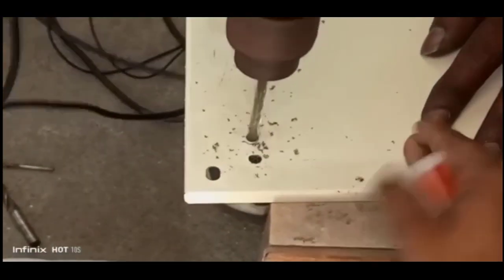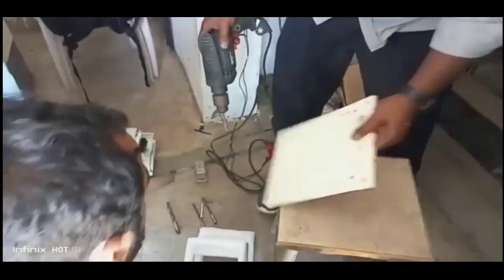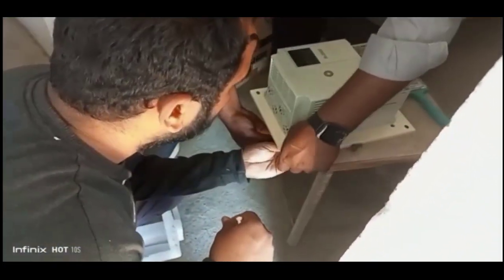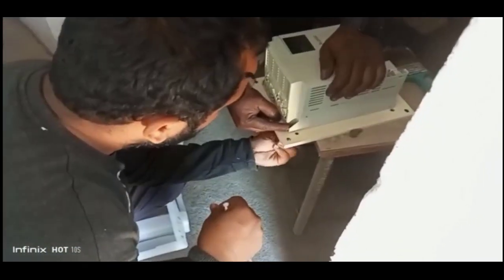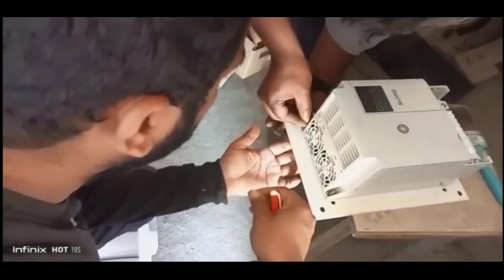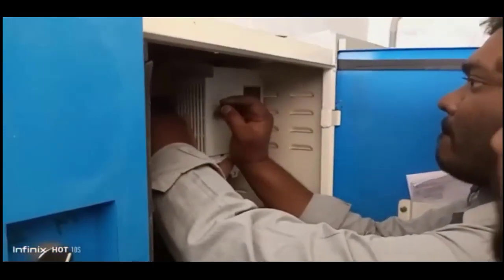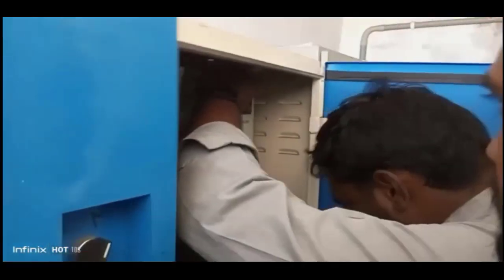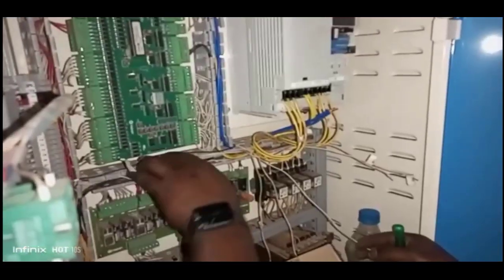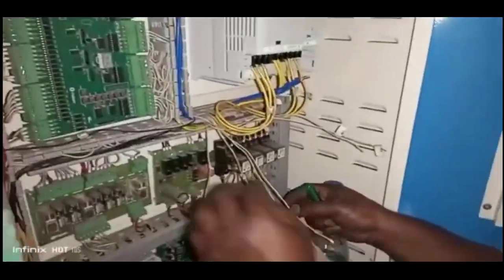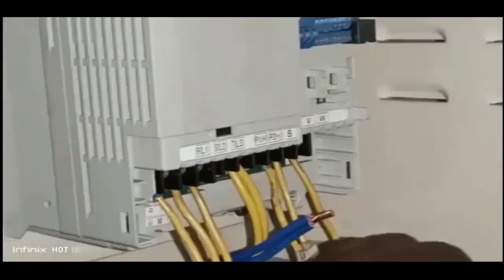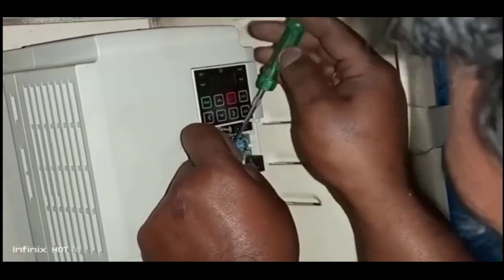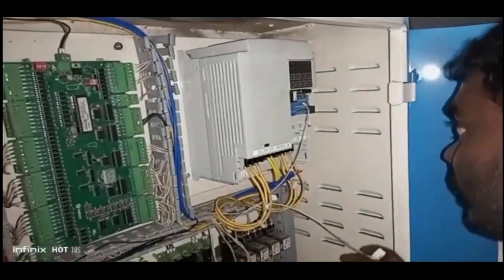First they are fixing that new driver board on the board by means of a drilling machine. They kept some holes. Through the holes they are fixing the new driver board to the board by means of bolt and nut. Again they are going to keep that driver board in the old place only. Now they are giving the connection to the motor as well as the supply and microcontroller sensors, for perfect operation of this driver board. I have already seen all these connections previously.